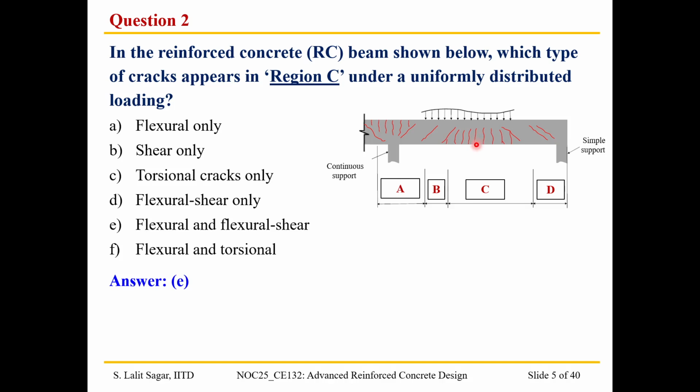These cracks are normal to the longitudinal axis. Then, after a certain depth of the beam, once the crack has penetrated into the beam, it tends to form flexural shear cracks because of the principal tensile stresses.